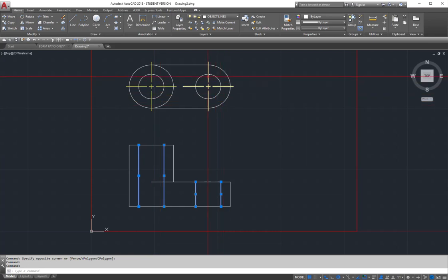As you will see in your exercise with your instructions, this is also a hole that goes through a solid surface. So if I just select them and drop them under the correct layer, in this case hidden line, they will become hidden lines. That is representing this part right here, inside of the outer cylindrical shape, as you will see on your pictorial drawing. Okay, and now what I need is my center lines to reflect this.